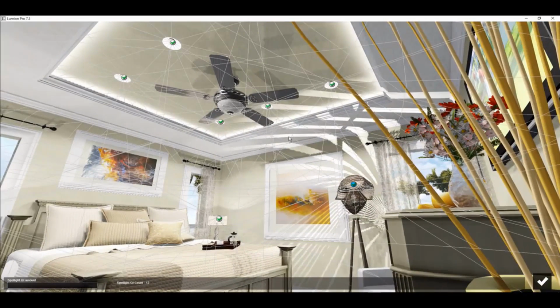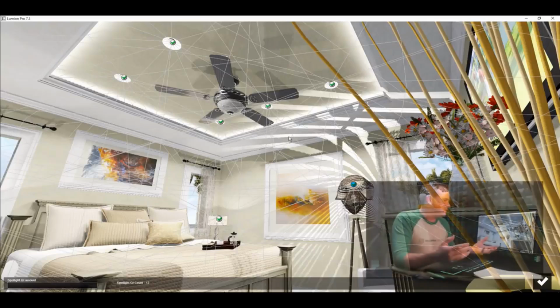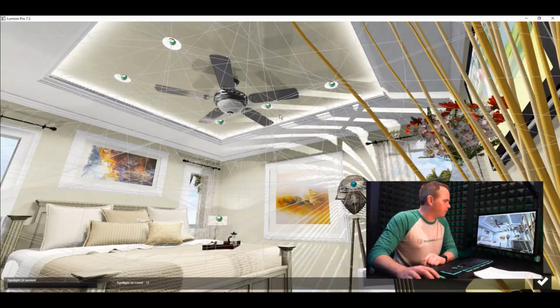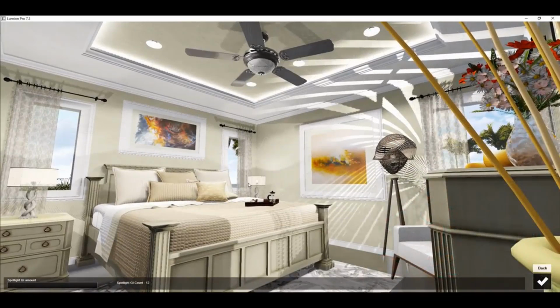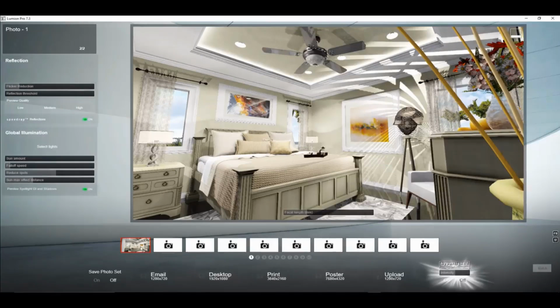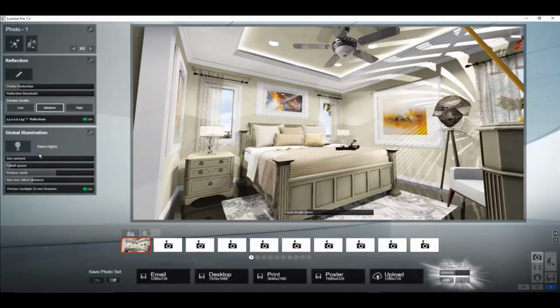That means that when these things are projecting light into the scene, that light will kind of bounce around and give me a more realistic render. All right, so I'll say okay. And back to that image, we do have preview on. If your machine is bogging down, you could definitely knock the preview quality to low and the preview for global illumination turned off.